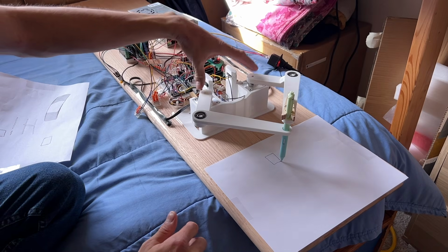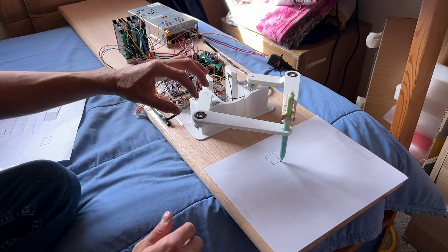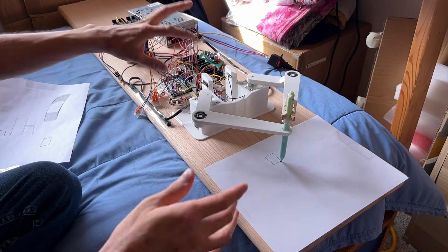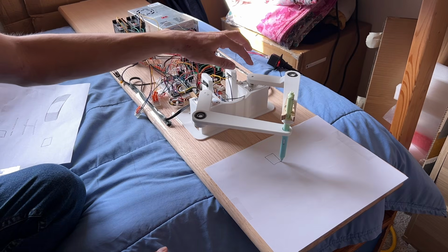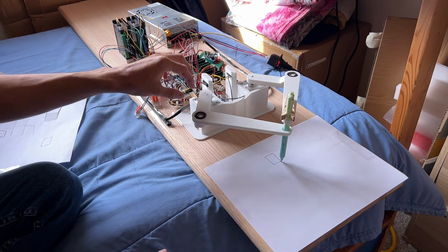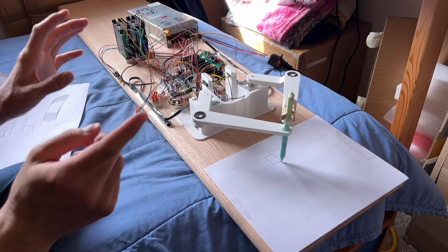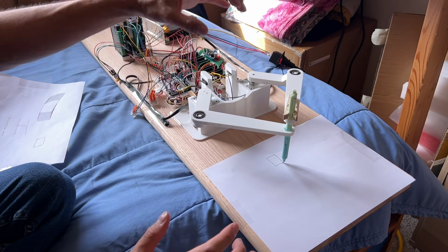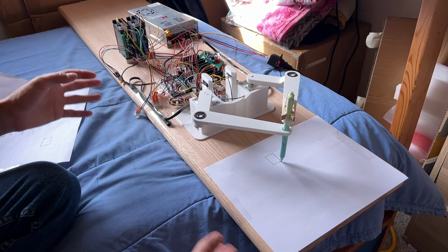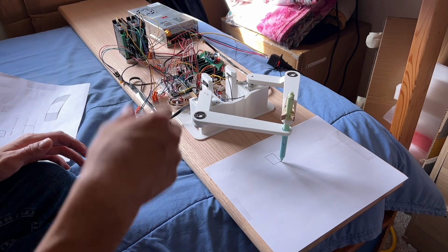Now, even though we have the encoders in here, I don't have the code set up yet to automatically recorrect where it should be. For example, with how it works right now, it will take the angle that it's at and the angle that it's got to get to, and then calculate the steps needed to take to get to that angle. And then it'll start just going through those steps. But with this setup, it could sometimes skip steps, which means we could fall short on the angle right there. And right now it doesn't even know that. It just knows that it got through all the steps and then it stops right there.